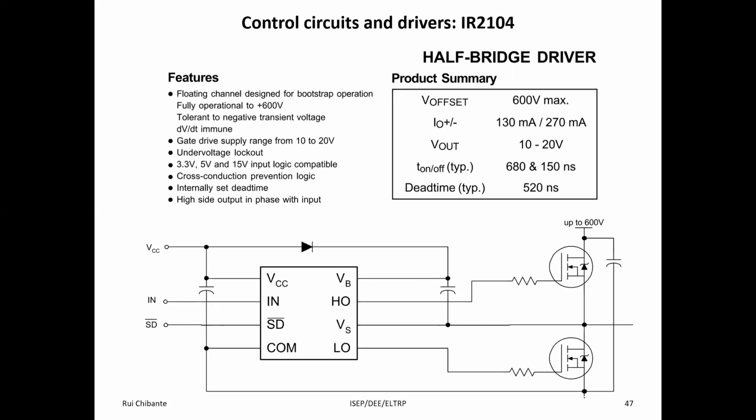Okay, this is the ground of the power part. It is the same for the control part. Okay, but now we have here two transistors. This is gate source from the lower device, and this is gate source from the upper device. That's why you call this the high side part and the low side part. Okay, if I want to use a gate source voltage equal to 10 volt, okay, here there is no problem. But again, this voltage that I apply here must be floating, because I don't have 0 volt here. 0 volt is down here.